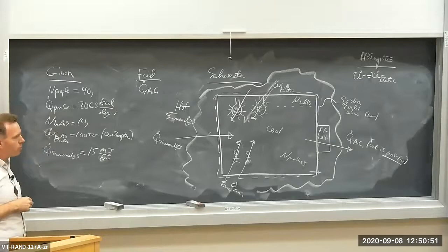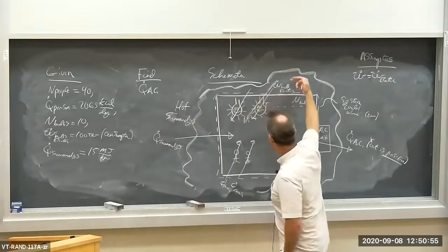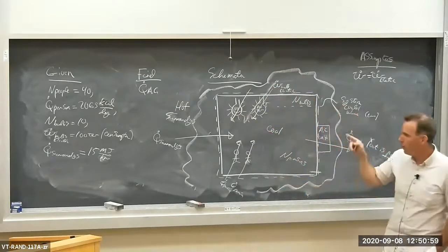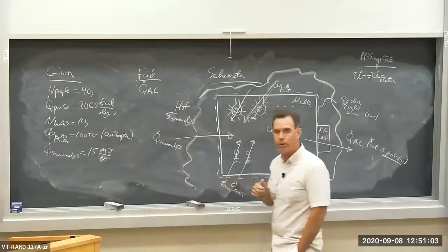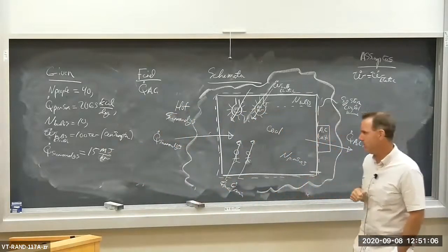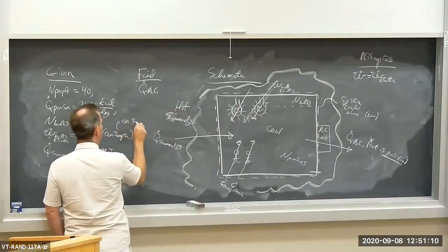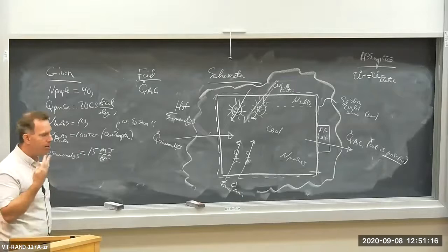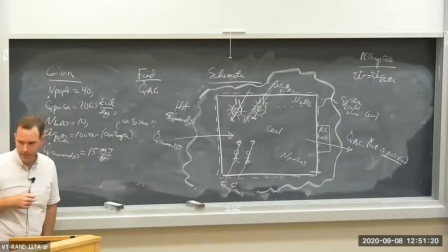In other words, we are doing electric work on the system. Electric power is flowing into the system to run the lights. So that W dot electric is on the system, not by the system. Consumption, or if you like, on system. So we're going to have a negative sign floating around here when we apply our energy balance, okay?